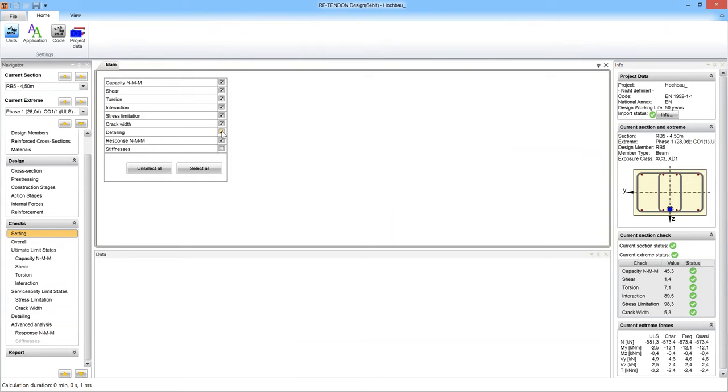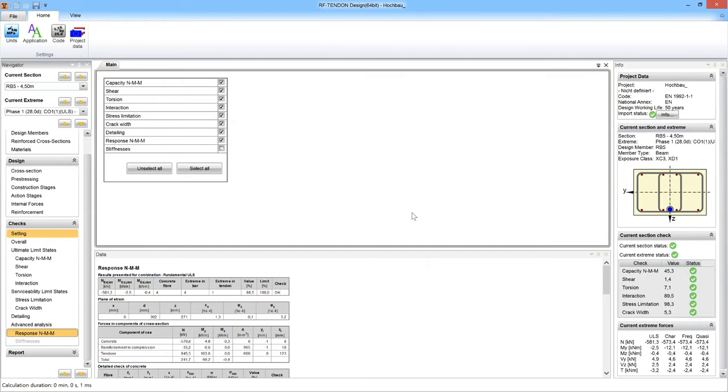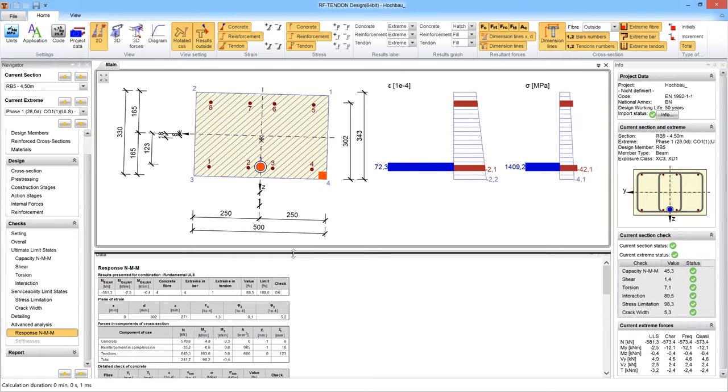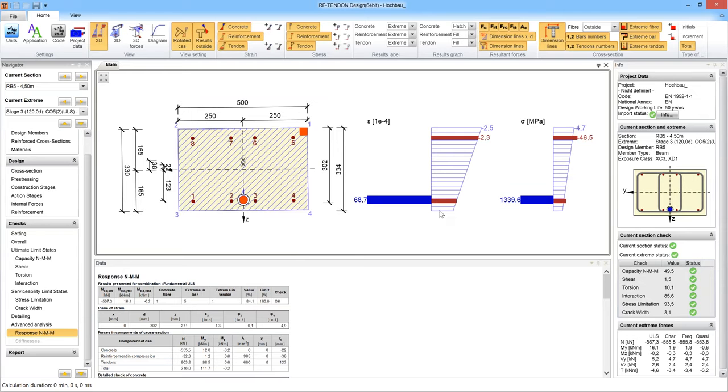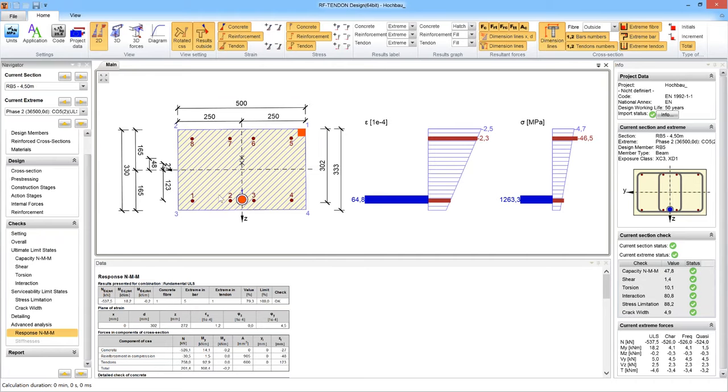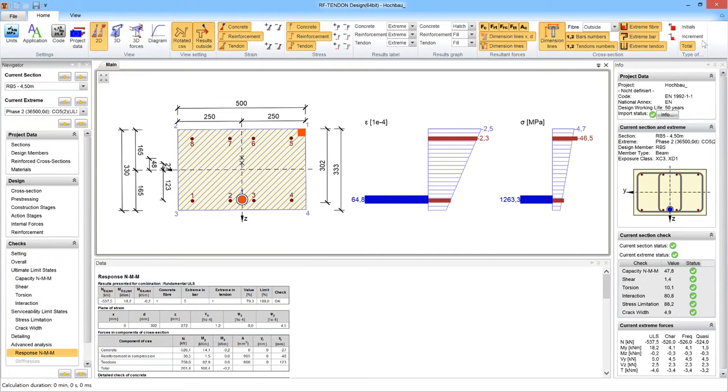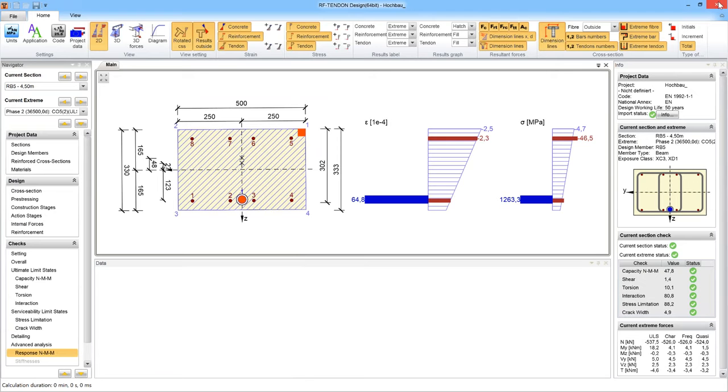It is not switched on now, but sometimes you have to switch it off because you do not provide a real reinforcing cage. And the response or stiffnesses, I can show here, and you can use this response to show all these stages. So that was at 28 days. You can see that there is quite significant pre-stressing at the bottom fibers. Then at 120 days we have some losses already, and also a higher load. So this is smaller, and at 100 years it is an even bigger difference. When we are happy with the design, then we can go back to